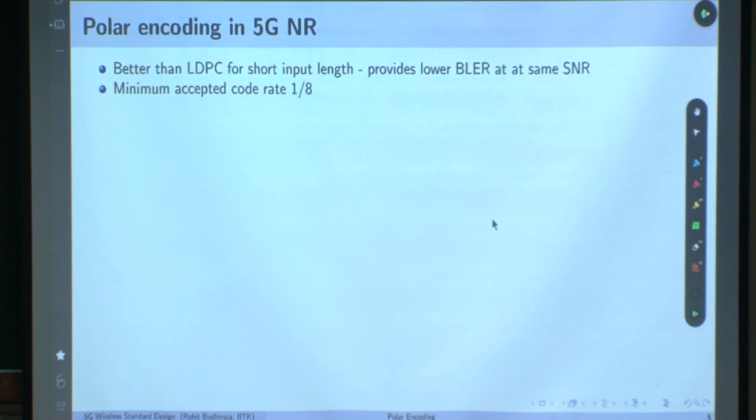So you'll essentially see that the PDCCH is encoded at a rate which is lower than your PDSCH encoding, because you want to give more protection to that, and that's the key idea. If you are talking about 1/3 there, we are talking about 1/8 here. And lower or higher rate, again, are achieved using rate matching. There are certain subtle differences between the rate matching in the PDSCH chain and the PDCCH chain. We'll see that also.